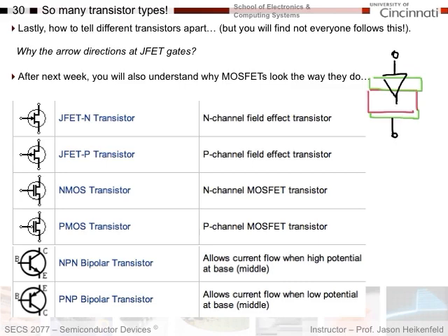And so if I were to get a lot of current flow and bias this the wrong way, the current flow would be into the device from the P to the N. And so that's why when I have an N-channel JFET, they draw the arrow there, meaning the diode is in this direction like I would have for an N-channel JFET. For a P-channel JFET, the diode would be in the opposite direction, hence the direction of the current shown in the opposite direction. So it's not the reverse saturation current, rather it's indicating the direction of the diode current, which you typically want to avoid.